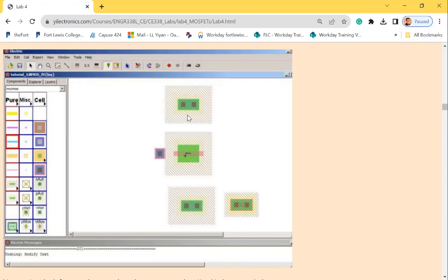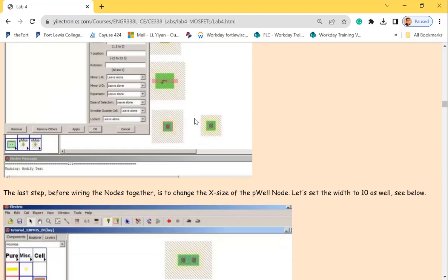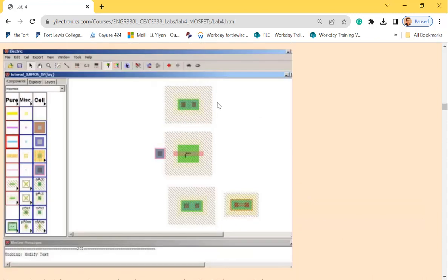Because I'm just telling you, these are the real physical view for fabrication. If you put this layer there and send it to TSMC or GlobalFoundries, they are going to make the exact layer for you. It's going to be a certain chemical being deposited on the silicon wafer. So you are telling them what you want to fabricate in the chip. It's not a schematic anymore. It's a physical view of the chip. So this is the NMOS, I guess. NMOS or PMOS? NMOS. So this is NMOS.